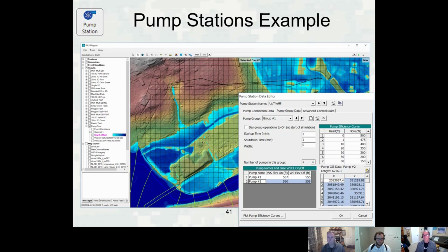This pump, basically the way it works is at a cell, there's a source-sink term for every cell. A source term means you're going to add flow in, a sink means you're going to pull flow out. So here where the water is being drawn, it's a sink term. It says for a given time step, I want this much flow, and that much flow over the time is a volume. Give me that volume of water, okay?